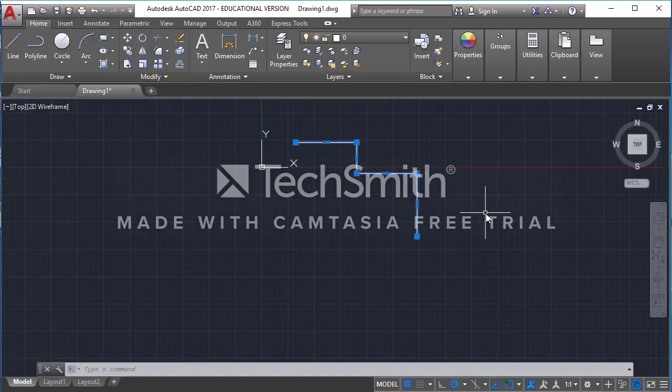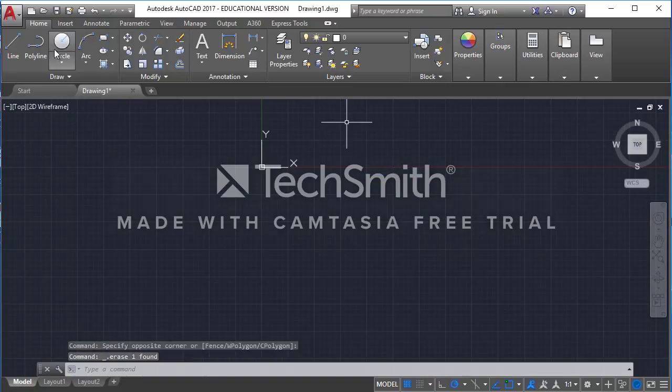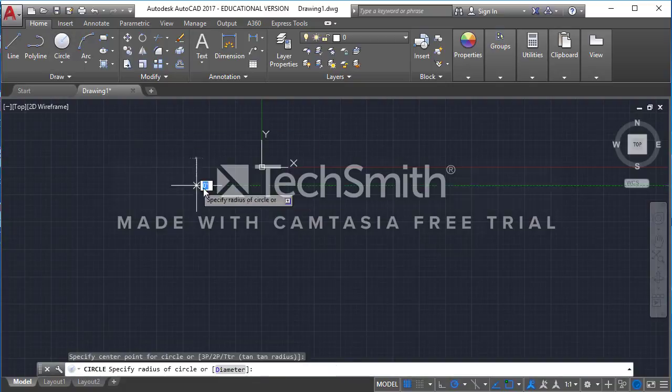I like to have a nice polyline when I'm doing the outer perimeter of my building. It's a little easier to manipulate your line at the larger scale when you use a P-line. So that's going to be the difference between line and polyline. Some of our other tools include circle.